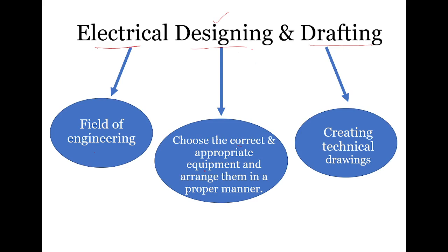This course or workshop is only for LV. LV stands for low voltage. Low voltage as per IEEE. As per IEEE, we classify the complete electrical system into two classes: one is LV and one is HV. The LV system is the system where the operating voltage is less than or equal to 1000 volts or 1 kV. Whereas the HV system is the system where the operating voltage, or nominal voltage, you can also call it, is greater than 1 kV.